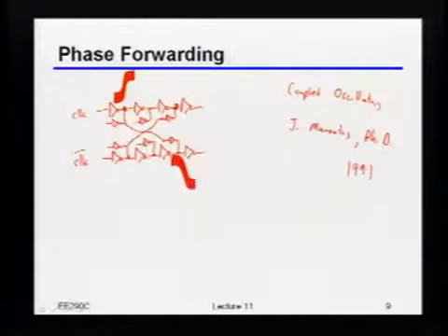So the question was just, how does it compare to using an inverter versus using a resistor? Basically, it's the same thing, right? The resistor just changes whether or not you've inverted to begin with. But conceptually, you have to size that resistor so that you guarantee that you're in the mode that you want to oscillate, right? And then depending upon the relative strength of that resistor or inverter compared to the main path, that will set how much you've sped up the overall operation of the ring, okay?